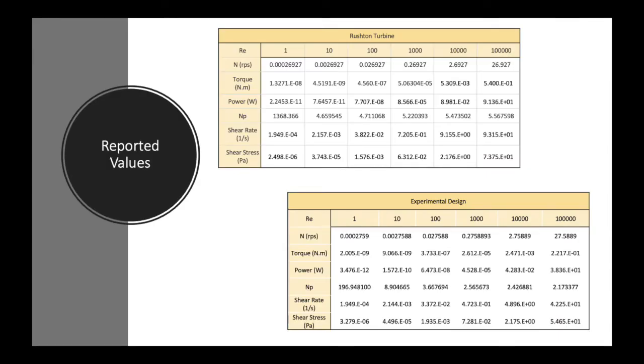As a starting point for the simulation, the rotation speed was calculated from the stipulated Reynolds number, using the viscosity, density, and impeller's diameter too. The latter is different between simulations, but as a factor of analysis will not be taken into account as the variation between them is around 1%. This rotational speed was assigned to the motion reference frame of the rotating zone to describe the impeller and shaft movement. As a general tendency, it can be seen that except for the power number, every other value increased with the growth of the Reynolds number and therefore the rotational speed.